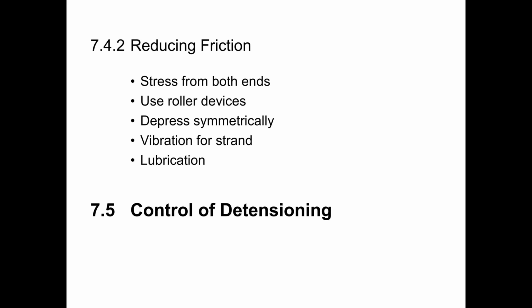Usually when detensioning drape strand elements, such as bridge girders, because it is a little bit more complicated, we have a sheet of paper with the detensioning sequence shown that's given to each of the torch operators so that they can assure that they are detensioning the appropriate strand at the appropriate time, that they're cutting the hold down devices at the appropriate time as well.